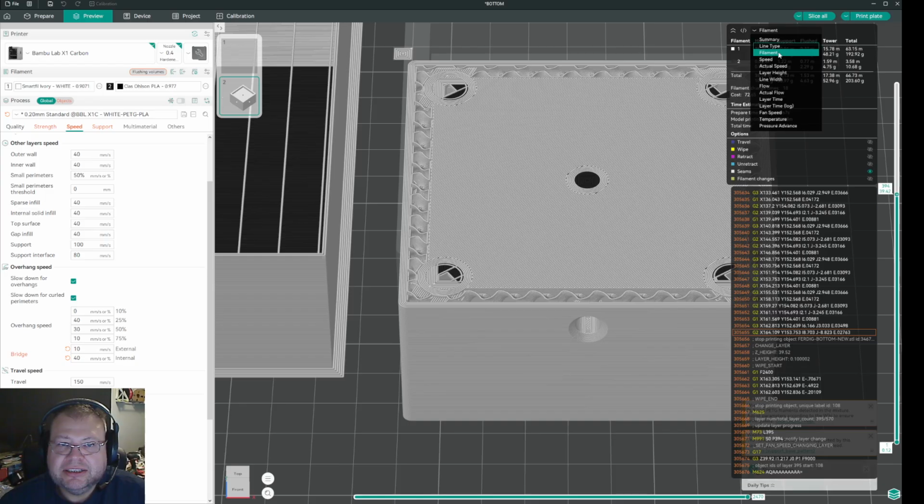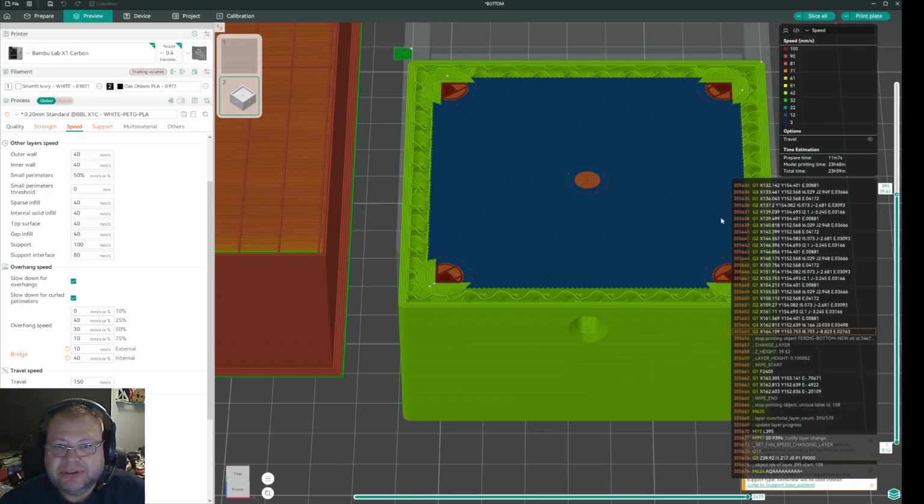So select speed again, and you will see you get an equal time here of around 3 millimeters per second. And this would make a much smoother surface because you don't have the difference in temperature, because everything will be printed with the same speed.